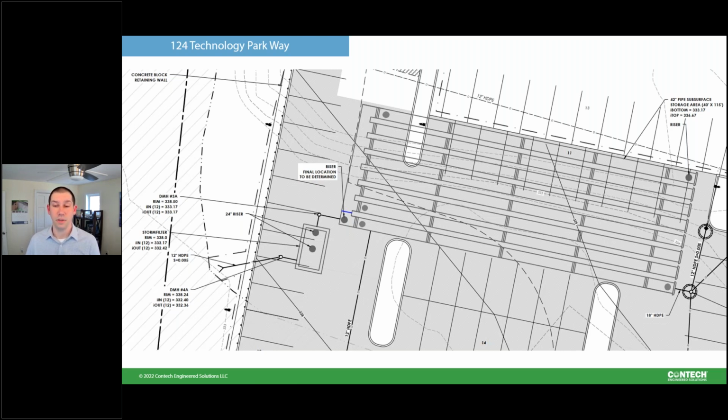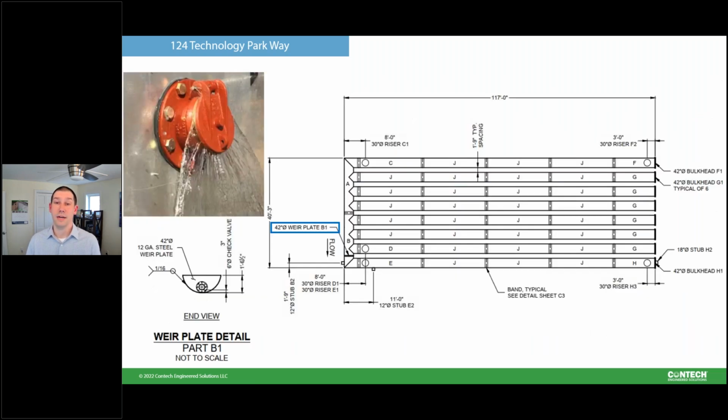So my intention was to fill the first row and then activate the storm filter with that, and then spill over that blue line that you can see in the middle of my screen. That's a weir. And so once it spills over, then you can capture the rest of the water quality volume. Therefore, you don't have to wait until the full storm before the storm filter starts to work. So there's nothing unique about a weir. It happens in many detention systems. It's just, how do you get it to drain back down?